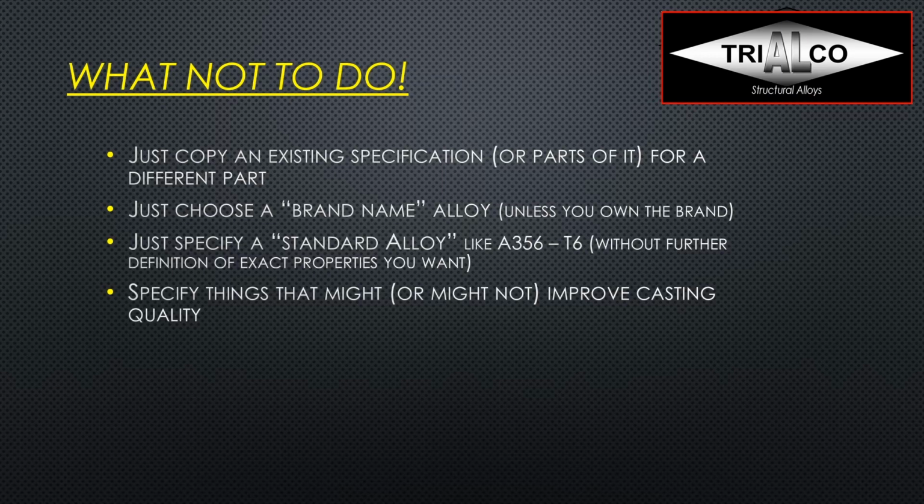Yes, but maybe you rather want to define what you actually need in terms of properties, because maybe somebody else is able to give you those same properties with a slightly different alloy, maybe a slightly different process, and you might even get it cheaper than you thought. Then specify things that might or might not improve casting quality. I love these phrases on a drawing or specification.